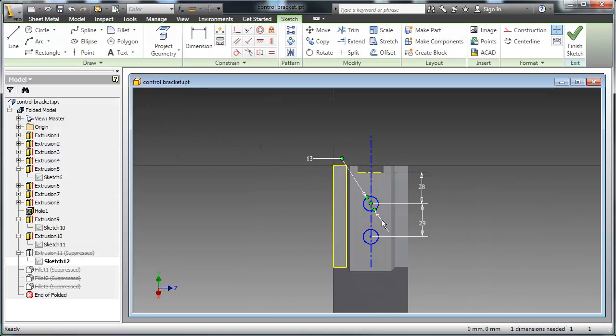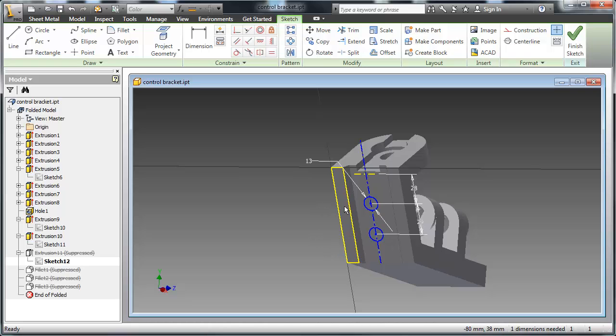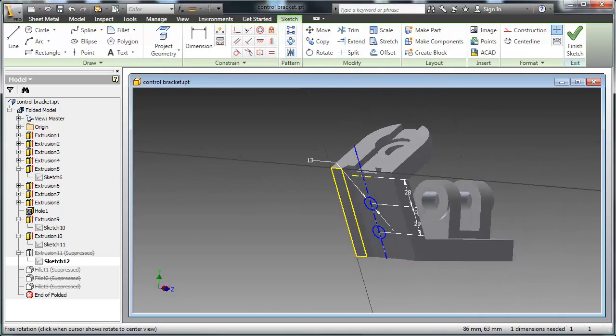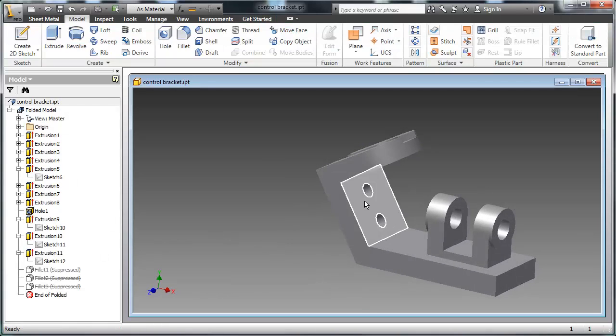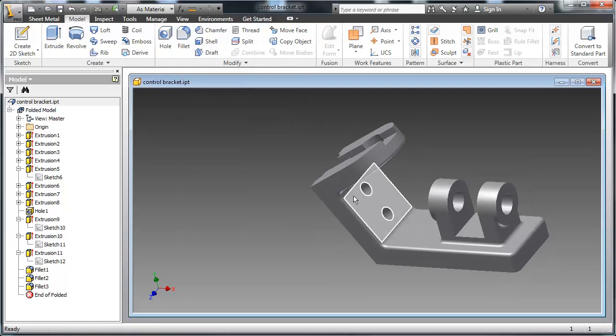Our next feature are these holes that cut through the neck of this part here. I started the sketch on this surface here. You'll notice that the sketch is hanging out in the air, which is okay. I located these parts, made sure they were connected to the center line, added the dimensions, and then extrude cut those through that part. Our last features here are the fillets, making use of the fillet feature here to add these 2 different size fillets here, and these 2 edges are 6mm fillets, and then all the others are 3mm fillets. This concludes the Autodesk Inventor interface.